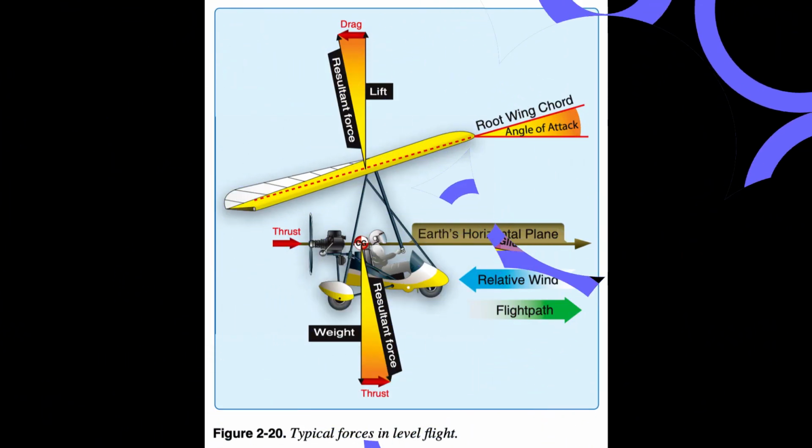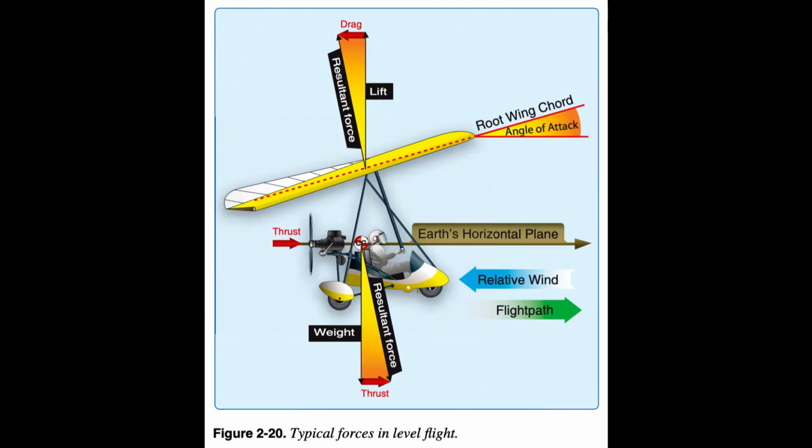Thrust. At a constant airspeed, the amount of thrust determines whether an aircraft climbs, flies level, or descends. With the engine idle or shut off, a pilot is descending or gliding down. Maintaining a constant airspeed, when enough thrust is added to produce level flight, the relative wind stream becomes horizontal with the Earth and the AOA remains about the same. As described for the airplane in the Pilot's Handbook of Aeronautical Knowledge, thrust equals total drag for level flight.